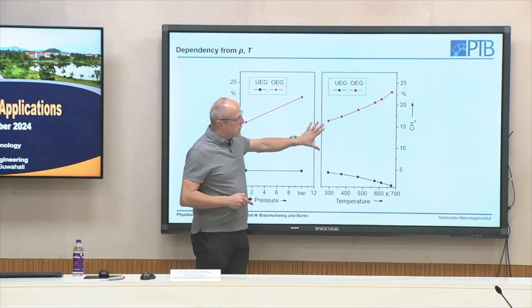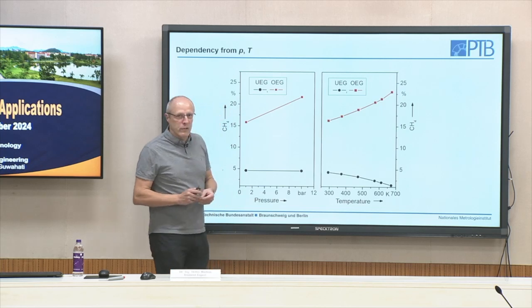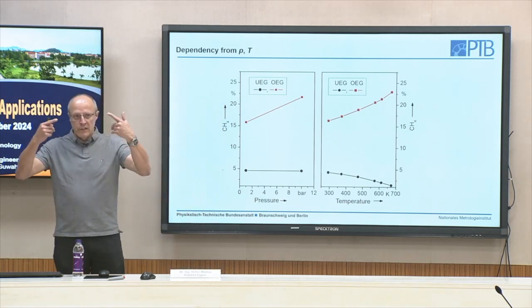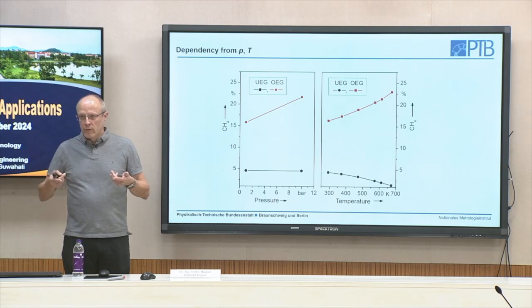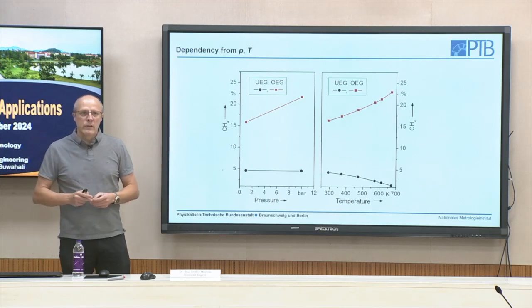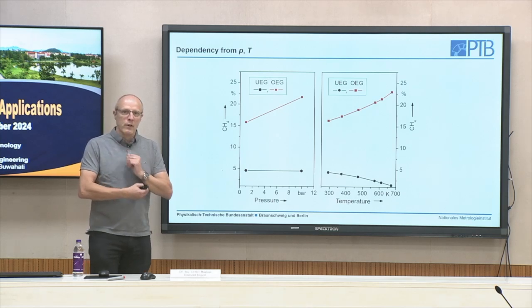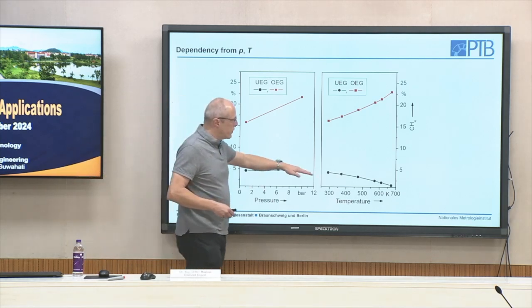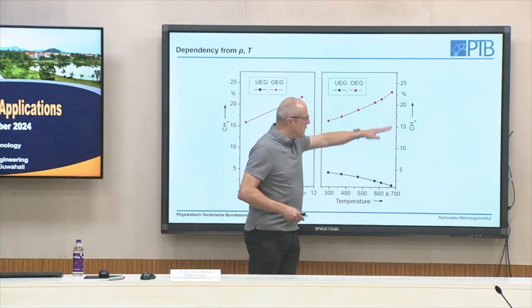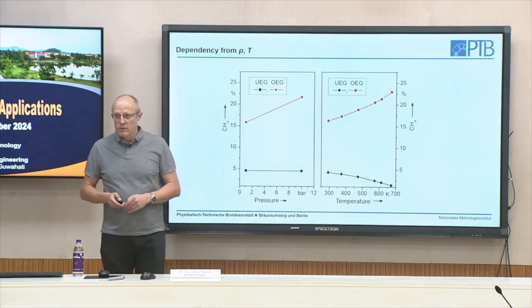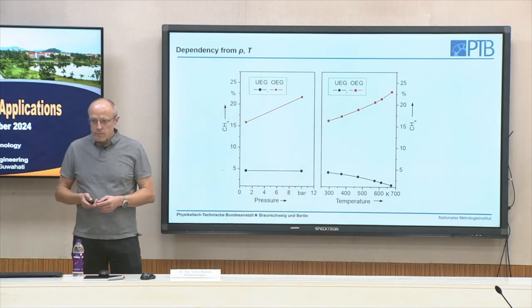And this is a kinetic effect. With the temperature, it's easier to describe. If you increase the initial temperature, you always increase the flame velocity. And therefore, the range is broadening. So an increase of temperature means that you have lower flammability limits and higher upper flammability limits.